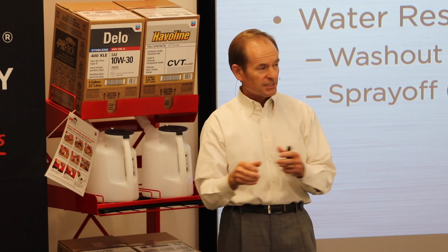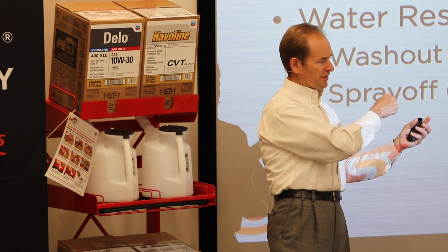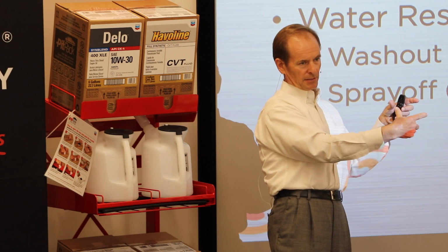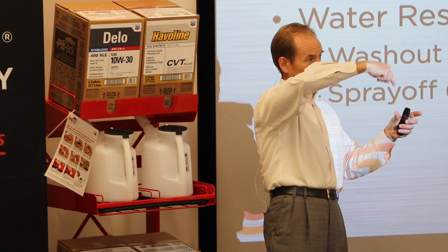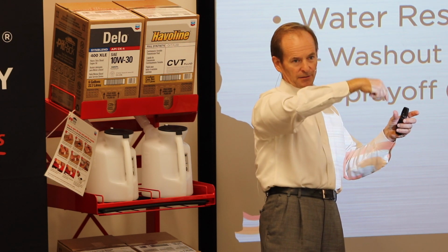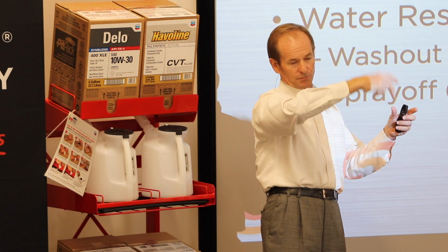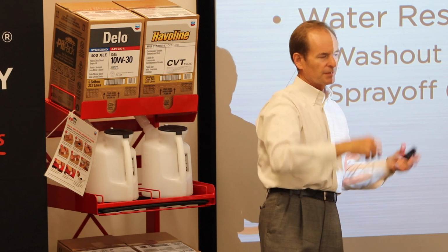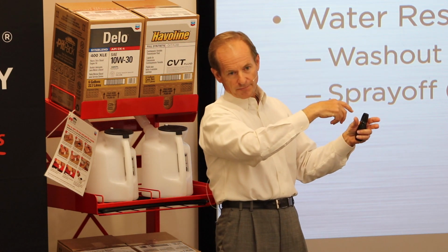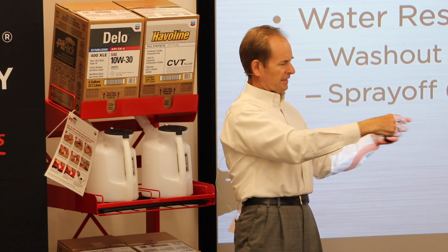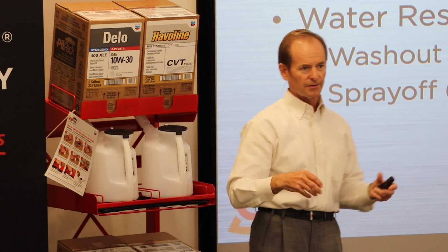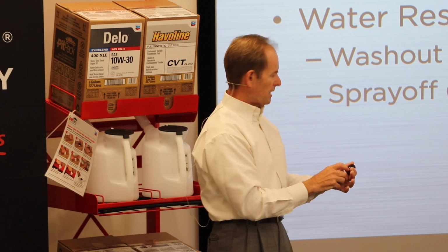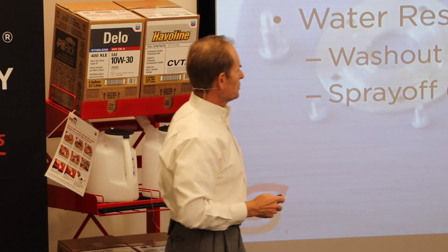Your spray-off test, you take your grease, you put a thin layer of grease on a little panel, and you put it in a box, and then you spray water on it at a certain pressure and a certain rate, certain temperature for an hour. You stop it, you take the panel out, you dry it off, and then you weigh it, and you see how much you lost there. Okay, so there are two different kinds of tests, and I'm going to show you each of those here.